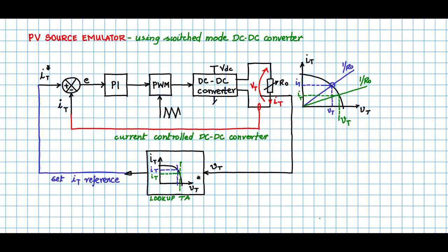The characteristic that you load into the lookup table is the one that will actually reflect here. So you can play around with the lookup table in terms of insolation, in terms of VOC, in terms of fill factors and all those things, and actually get a replica at the output at the higher power level. And this you can design for any power level that you want.